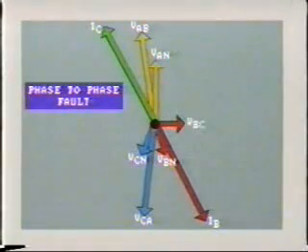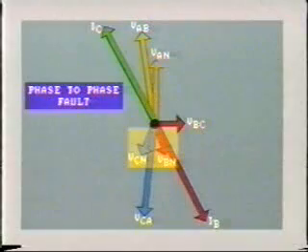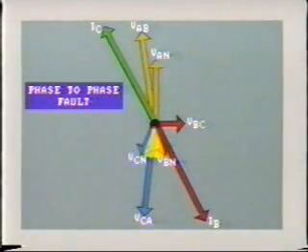The short circuit drastically reduces the difference in voltage between lines B and C, that is, VBC. This reduces phase voltages VBN and VCN, and the angle between them to less than 120 degrees.